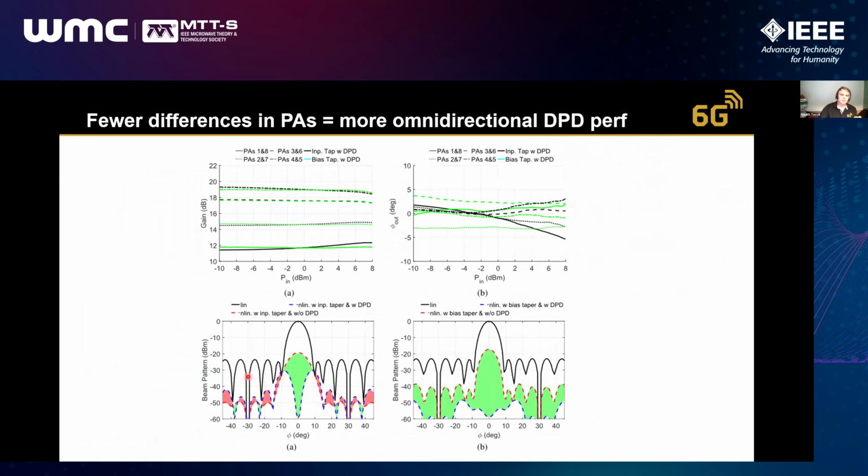Here are simulation results still, but you see that the biggest differences between the different techniques were not in the AM/AM, but in the AM/PM. So when we controlled the bias points of the individual amplifiers, we were also controlling quite strongly the phase of these individual amplifiers. Then we had to compensate that with the phase shifter with some external calibration. But after we did that, we were able to achieve quite linear AM/PMs for individual amplitude levels.